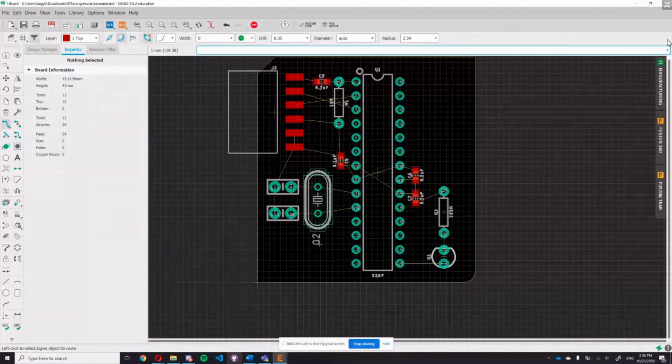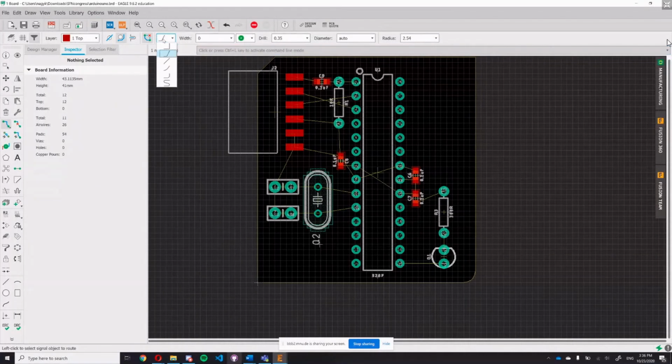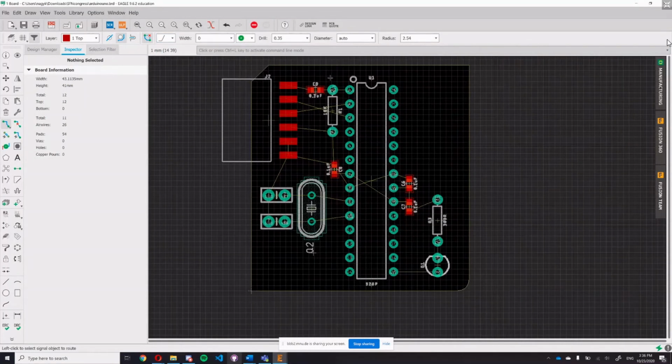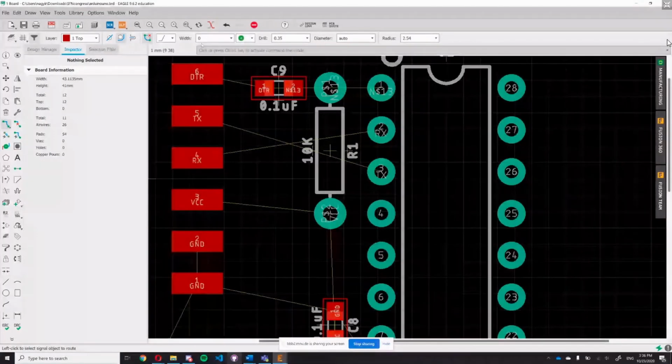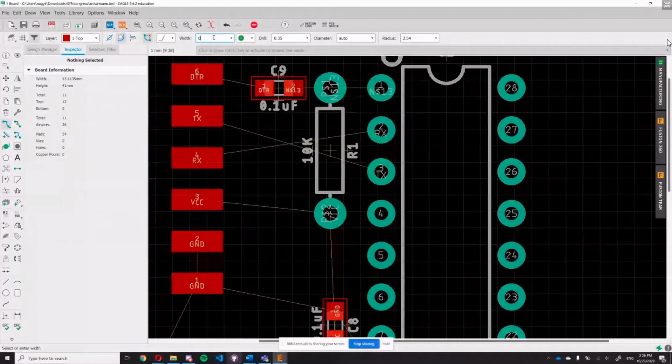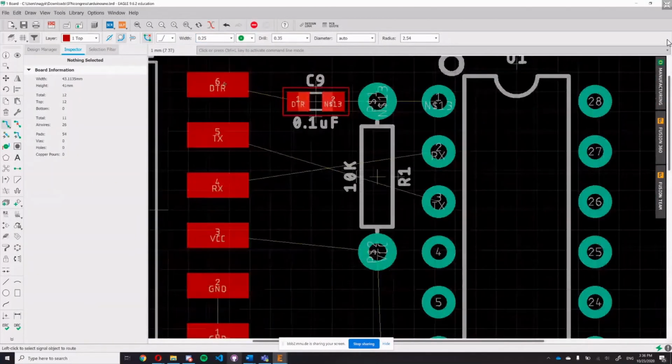So you have this tool, and let's go through the settings. You've already seen this bend style, so we can keep the basic bend style, the angular one we have here. And here you don't want to have zero width wires. For the signal ones, we can do, for example, 0.2 or 0.25 millimeter wires. And we can start with that.